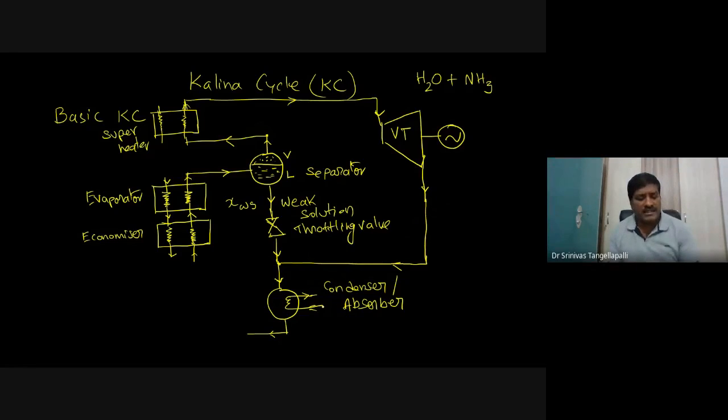So as I told in the earlier introduction of the Kalina cycle system, this mixture is zeotropic in nature. And in a zeotropic mixture, these two fluids can be separated by adding heat. See, here we are adding the heat in the boiler. We are able to separate the fluid, and also we are able to mix the fluids. Here, two fluids are mixing by rejecting the heat. The mixing process we are calling the absorption process. The vapor has been absorbed into the liquid part, which is having lower concentration. So this mixing process, that absorption process, takes place at the inlet of the condenser.